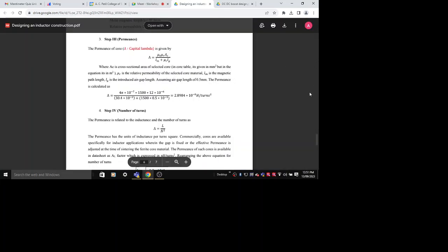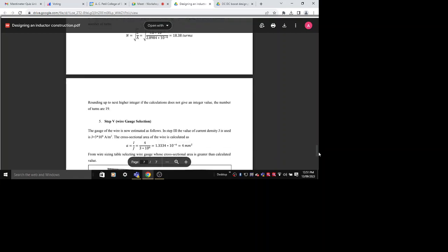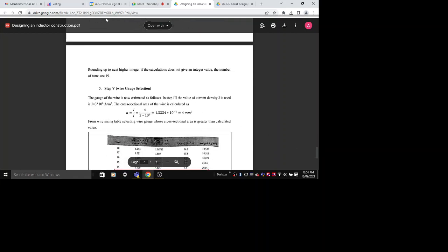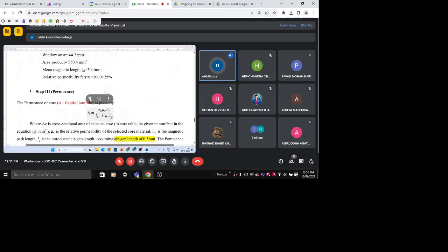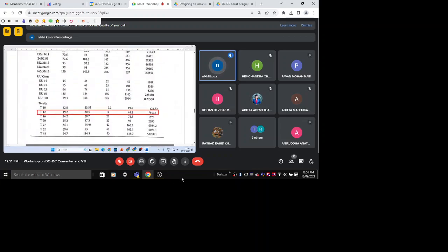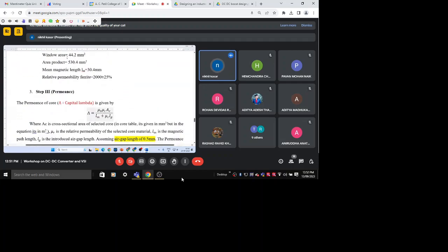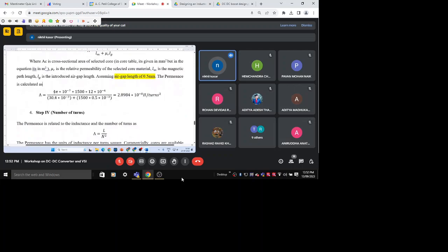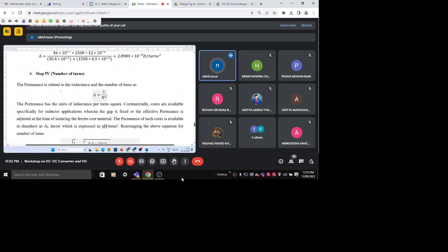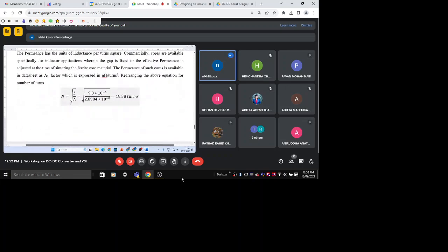Yes, I hope you are with me. We started with area product. We selected that higher area product for the toroidal core. T12 toroidal core we have selected. We have referred all the values. Using the values from the core table, we calculated the value of permeance.